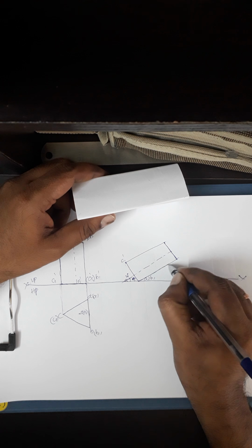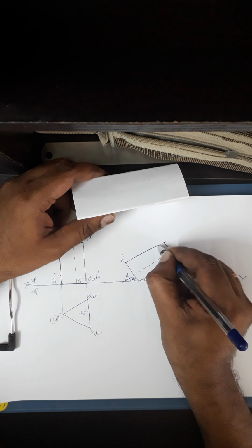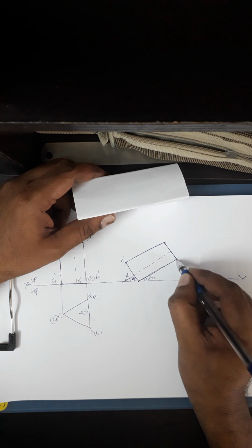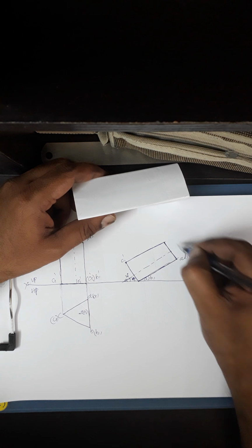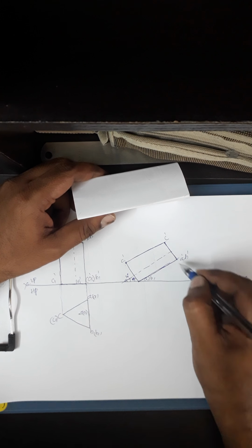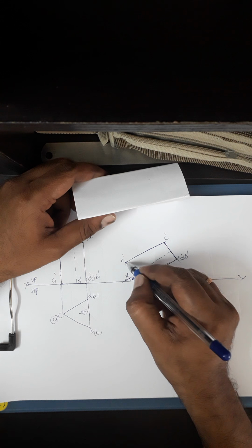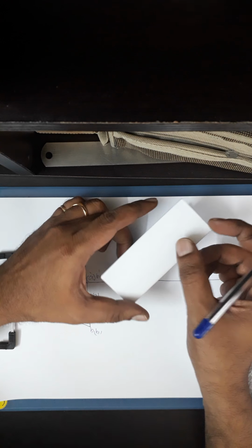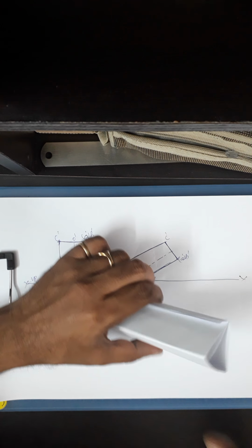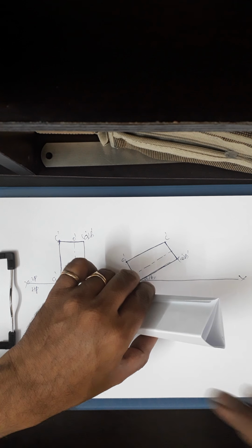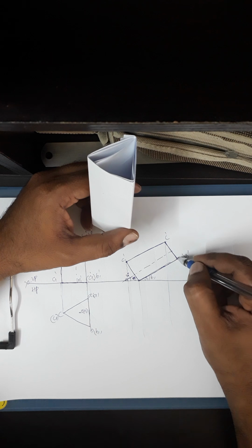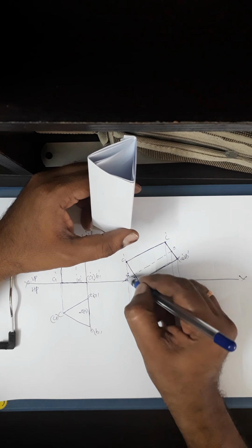So then this will be the view, the same view redrawn in this position. This method is called the change of position method that you have learned in your projection of planes. There are two methods, the change of position method and the auxiliary plane method, right? So I am drawing this by the change of position method. In this position, this is your front view. How exactly does it look in the top view? When it is turned in this position, that is your view. So I'll project all these points on HP, including the axis and O1 dash.